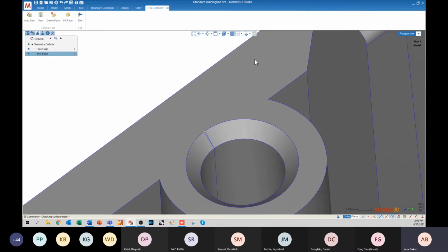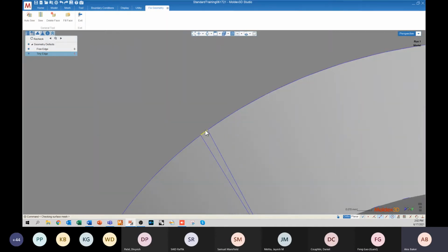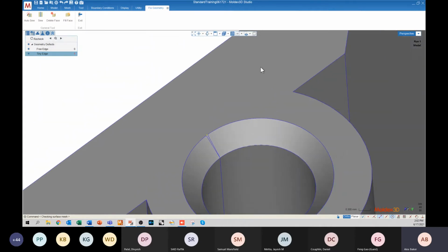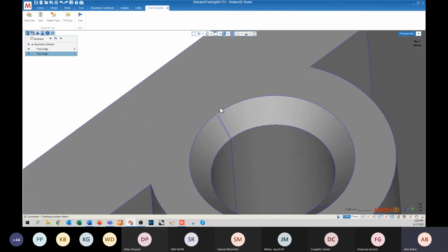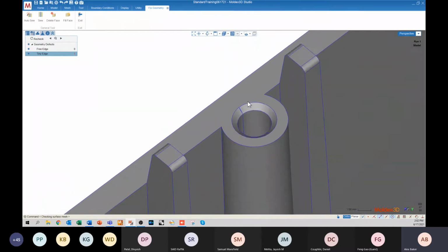So for example, if my triangle size is relatively large out in the middle of my surface here, we can see that this feature line is going to dictate that the size of the triangle needs to be really small, which means that eventually I have to go from the large size triangle to a smaller size triangle. And that mesh size disparity can actually cause a propagation of error in the simulation. When I say error, it's more of an inaccuracy in the simulation due to mesh quality specifically.